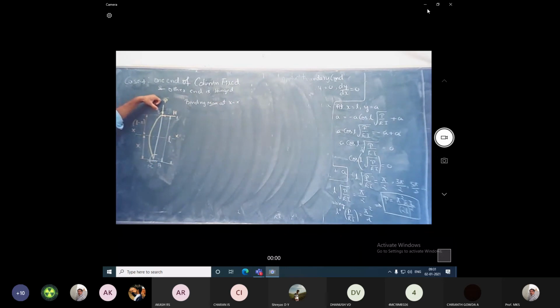Since it is deflecting such that there is a concave surface with respect to the initial beam, you can see the concave surface here at the inside nearer part of the beam. So therefore the moment will be negative here. With respect to the previous third case, it was positive since there was a convex surface with respect to the initial beam. Here it is a concave surface with respect to the initial beam, so it is negative.